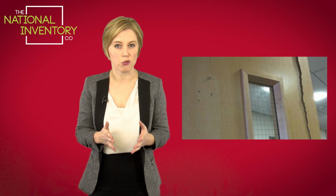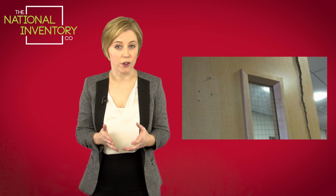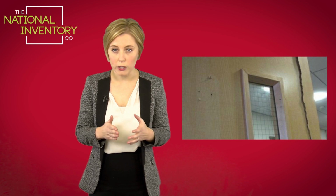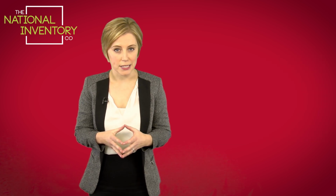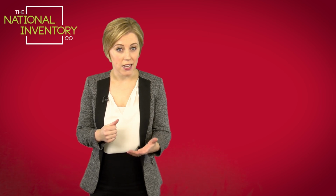Often you'll find tenants have screwed hooks for their coats into the door, or where the door panel has split from their excessive opening and closing, or hanging things over the top of doors. Any such damage to the surfaces of the door will reduce the effectiveness of the fire door. During your inspections, you will be required to look for these things because this is a breach in a fire door, and it's important that you highlight this breach, and more importantly, at time of inventory, it's important for you to note that there was not a breach and the photographs are provided to show that evidence.